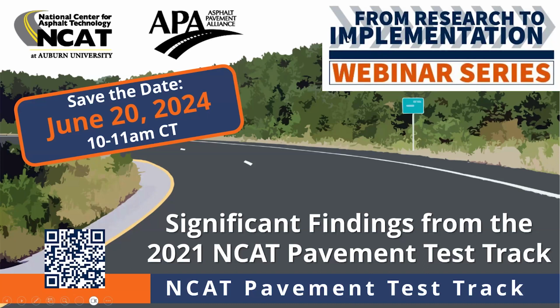That is a banner for the additive group experiment that we have on the track right now, and some ongoing research for the Oklahoma DOT with an engineered crumb rubber mix that's a balanced mix design as well. So the jury is out on how big a benefit it could be, but when you have an elastic black sand in your mix, which is essentially what the ECR stuff is in my opinion, then you would expect there to be the potential to have some fracture benefits.